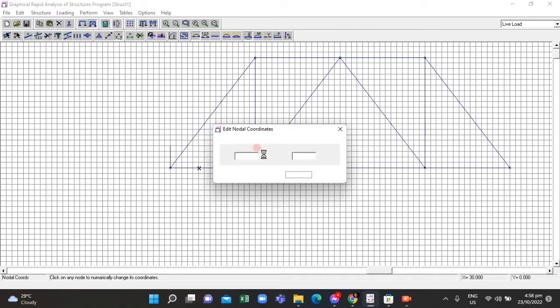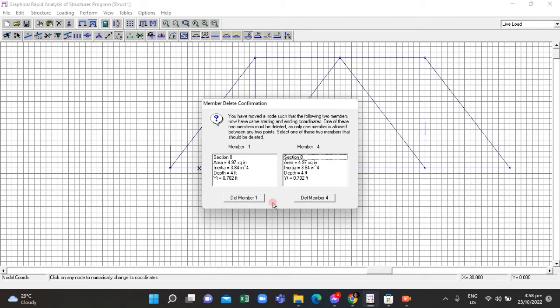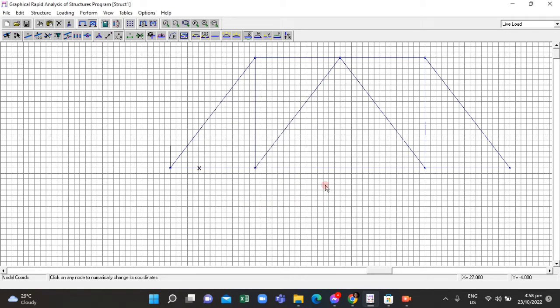And this node, I'm gonna remove this. I'm gonna remove this node since it will probably cause an error upon executing structural analysis, since the stiffness matrix on this truss structure will be undefined, or will not be defined by the function or the formula given or the program in this software. So let me check if the materials are correct. Double check, so they're correct. So I'm gonna proceed with adding the supports.